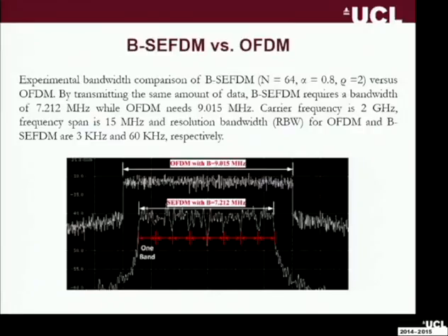And this is the experimental result. Here the actual amplitude is exactly the same; we've just shifted it for illustration purposes. The bandwidth you can see here actually relates to an LTE standard, but the number of subcarriers does not. An LTE standard has 601 subcarriers. Here we're only trying 128, and the reason we want to do that is just to compare OFDM to SEFDM. Okay? I'm going to speed up a bit now because I'm a bit conscious of time.